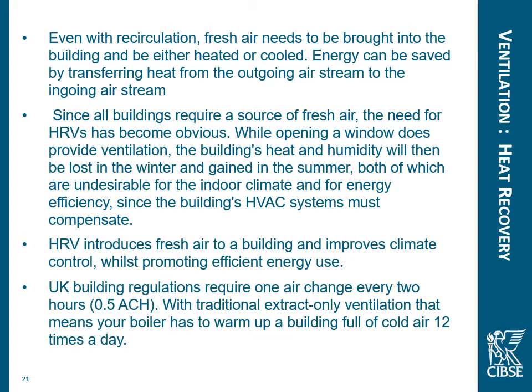If we think about UK building regulations requiring one air change every 2 hours, that means we're actually swapping the air in the building 12 times a day. Well, what we don't want to be doing is throwing away the heat 12 times a day. We want to heat the building once, swap the air in the building so people can breathe and have fresh air, but hang on to that heat. So how can we do that?